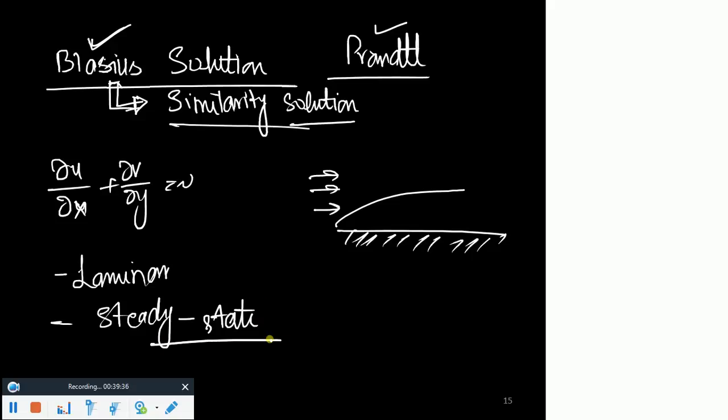And then you have steady state, right? And generally, to keep things very simple, he took it as 2D, right? Now, what he did was to find out the velocity profile. You remember that the friction or shear stress is dependent on the velocity profile. You need to take partial u by partial y, and for h you need to take partial T by partial y. Okay, it means you have to solve those Navier-Stokes equations first, and then you can come up to those expressions.